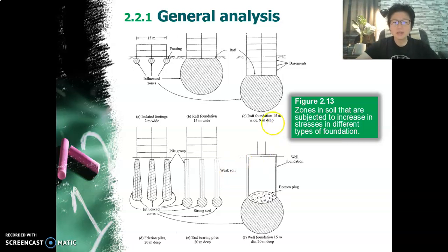Go back to this. Now for a caisson, because it's empty inside, and when the load starts to go in, alright, you can see that the pressure bulb is the same. The influence zone starts from the base of the caisson wall or the foundation. However, because it's hollow in there, you could actually find that there is this plugging effect. Some of the soil pushes itself into the cavity or this space in the pipe. Whether it's good or bad is debatable.